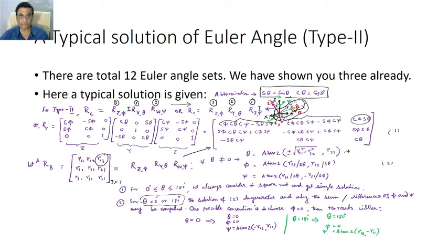If it is a passenger aircraft, it's very unlikely that the aircraft situation will be like this, or it will be completely like this. So the gimbal lock situation or degenerating situation will be rare. But of course, for a fighter plane which is maneuvering like this, the gimbal lock could be a reality. So gimbal lock is the inherent problem of Euler angle representation, right?